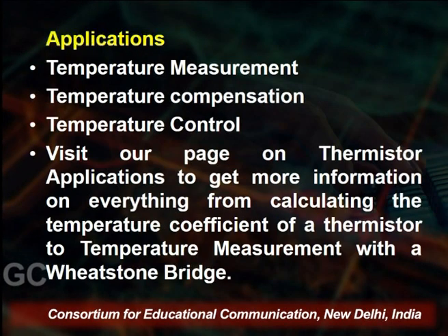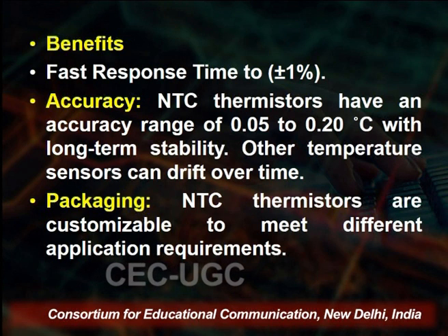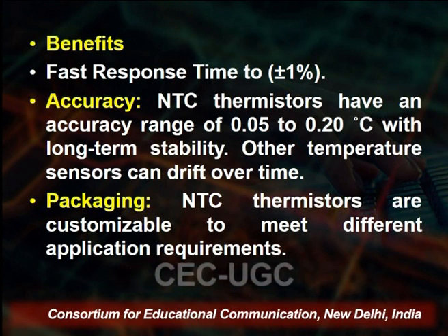Now what are the applications of this? As we discussed, it is used for temperature measurement, compensation, temperature control, and thermistor applications. And what are the benefits? It gives a fast response time and approximately plus or minus 1% accuracy.